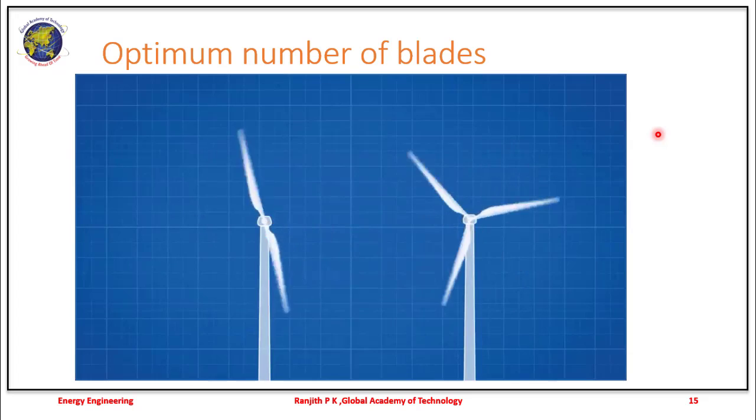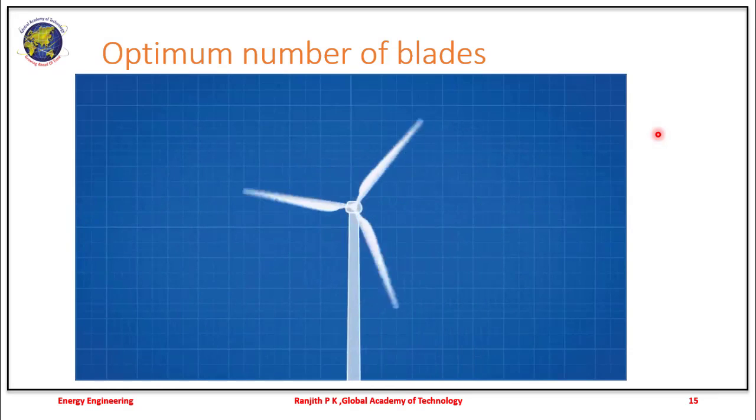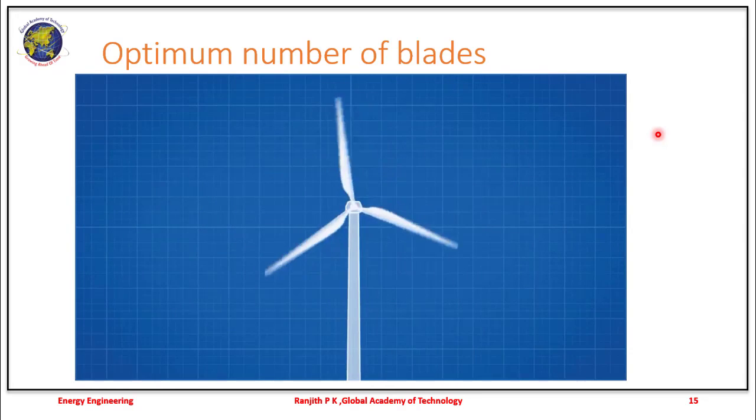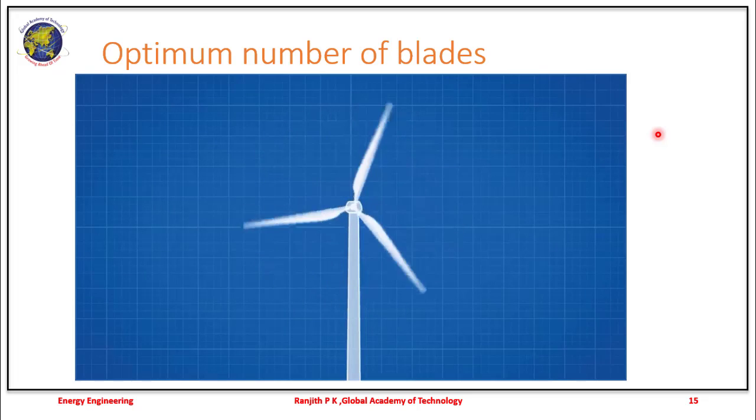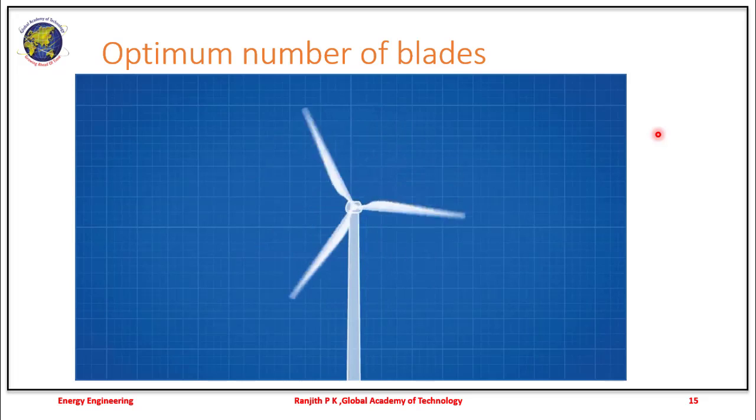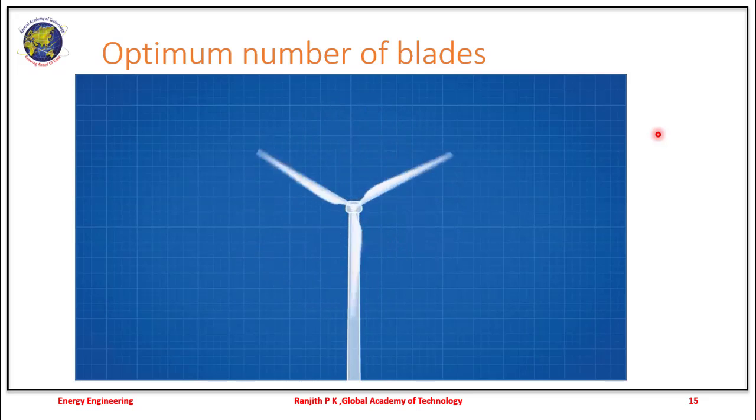So a 3-blade design can generate more power at slower rotational speeds than a 2-blade design, while being more cost efficient than a 4-bladed option. So the 3-bladed design is our Goldilocks choice, not too much and not too little.